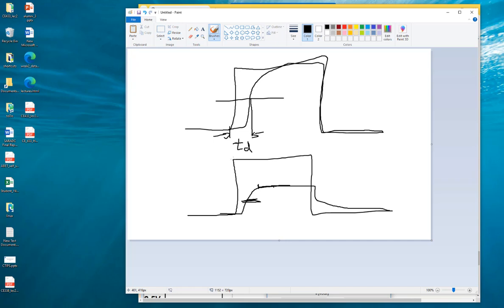So what about the rising edge here? 50% or 25% or somewhere else? So 50% here doesn't make sense, right? We can directly draw a line because they all reach the same voltage. But for the input rising edge, what time should we use though?